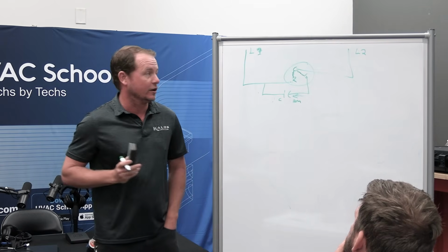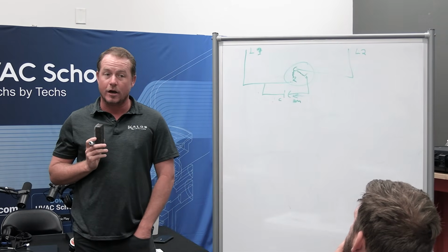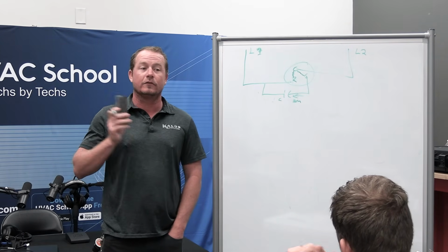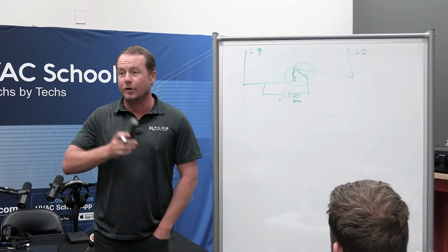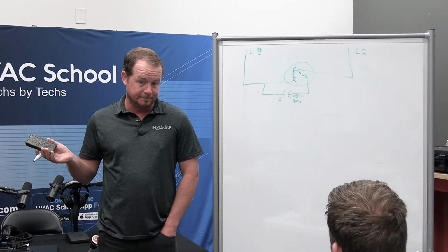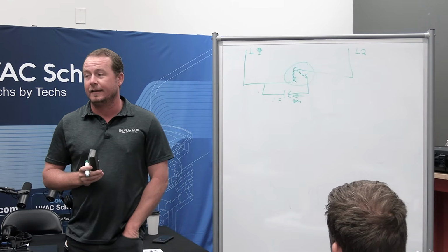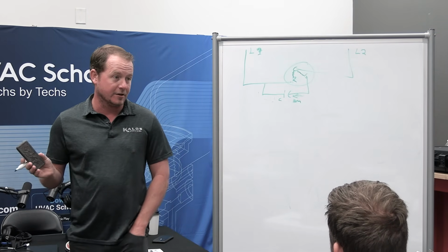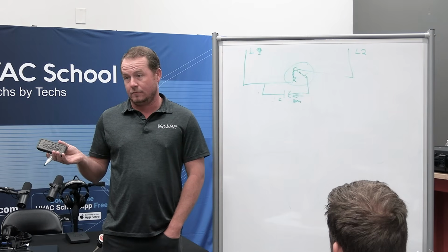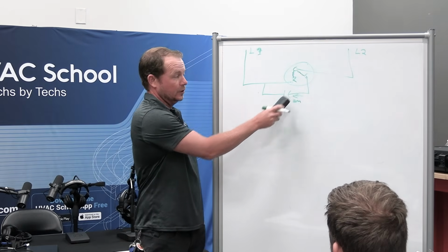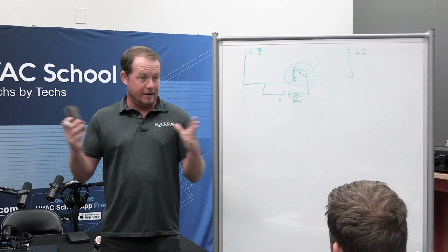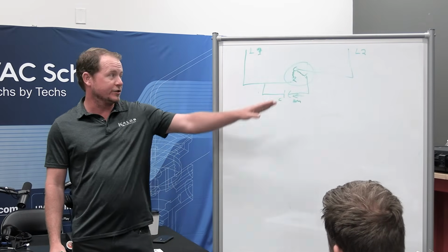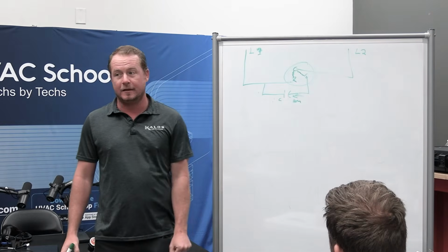Does that result in stress on our start winding? The answer is no, because if the start winding has a capacitor that's too low, then the amount of current moving through it is low. And when you have low current, you also have low heat. What happens in our start winding if our run capacitor is failed completely? Nothing, right? Because without this balloon filling up and discharging 60 times per second, no current whatsoever moves through our start winding.